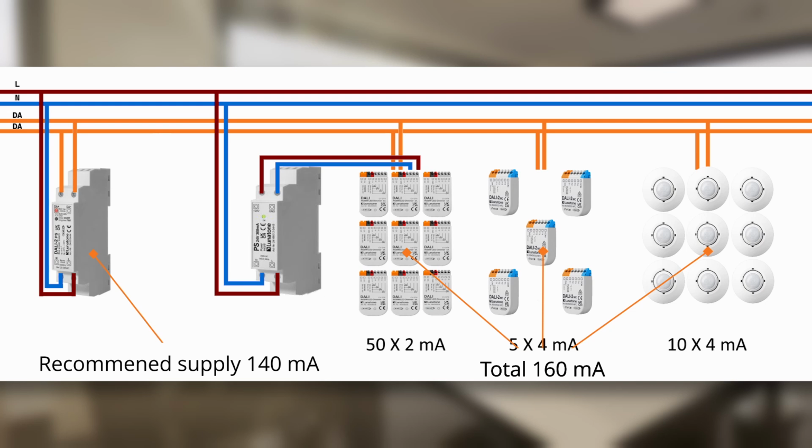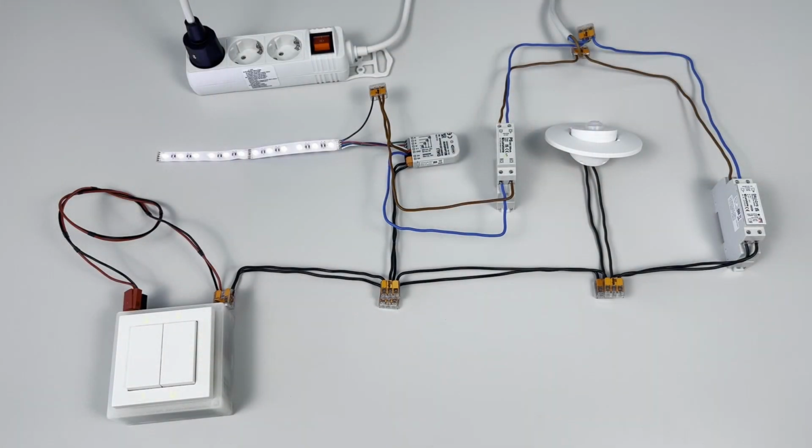Depending on cable length and cross-section, the system may become underpowered, meaning that the power demands may occasionally exceed the supply capacity. In certain cases, system behavior can become unpredictable. It may still function normally when all devices are idle, but failures may start to occur when multiple devices become active at the same time.